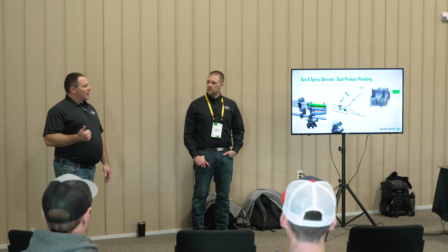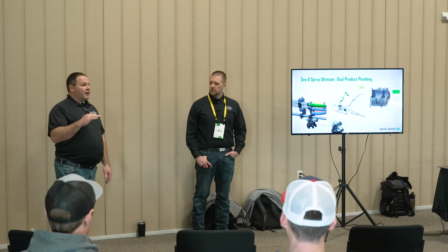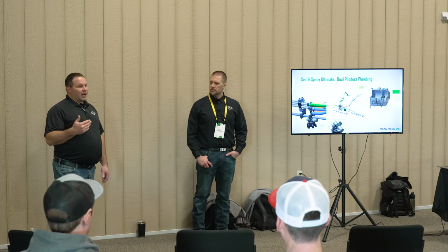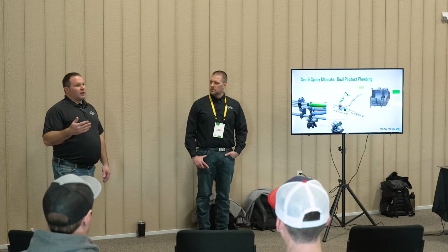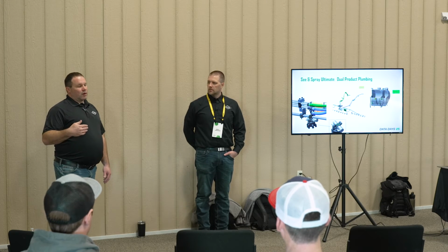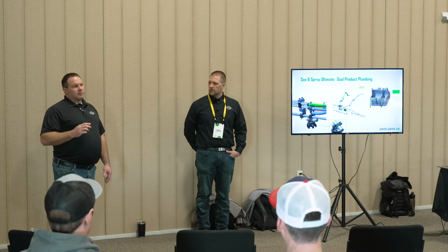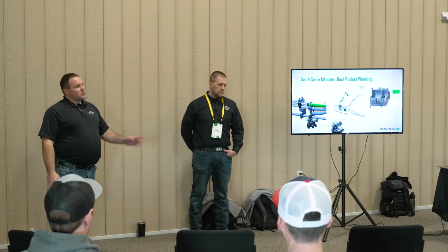If we talk about fallback mode or fail-safe modes in both sprayers, if we're above our crop height, too low, or going too fast, our machine will go into a fallback mode, which would be to spray all of the crop with that section or part of the boom that's going too fast. So going to Boom Track Pro Ultimate or a See Spray Ultimate machine, we limit the risk of that happening more often. So we can talk about plumbing as well.